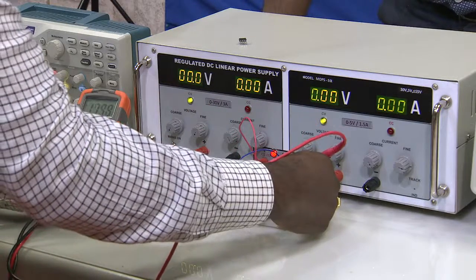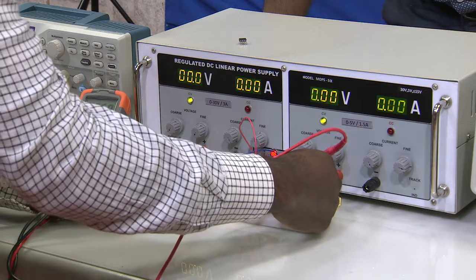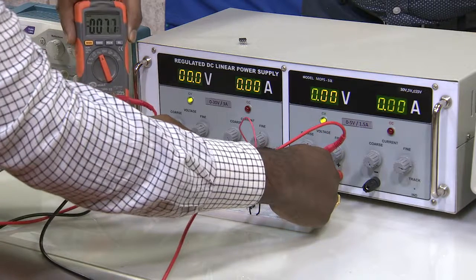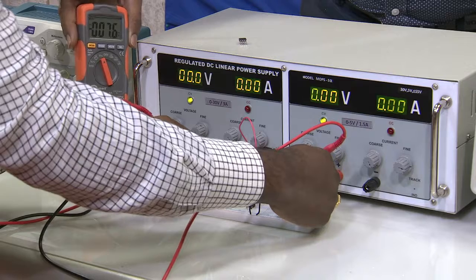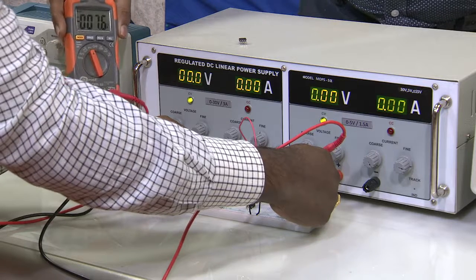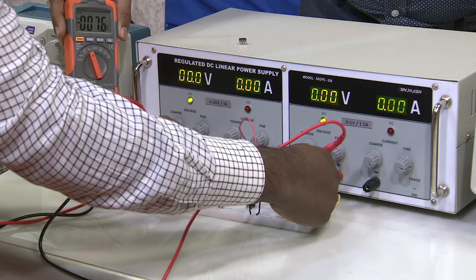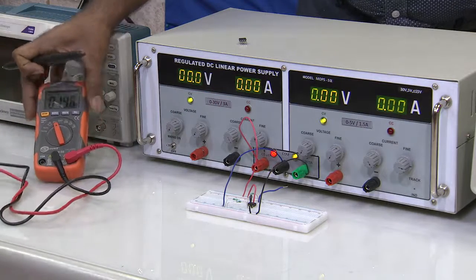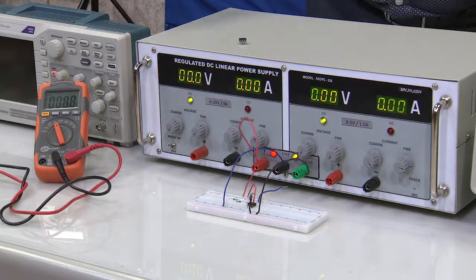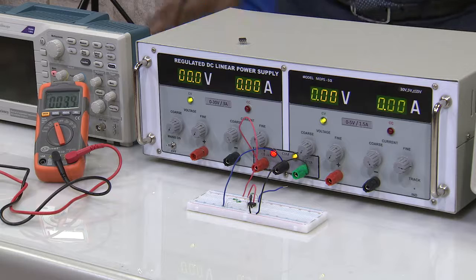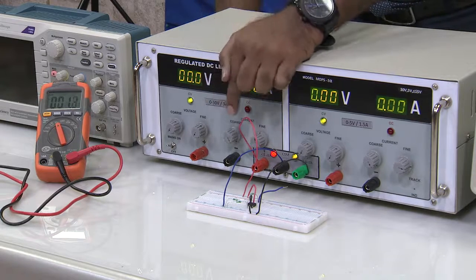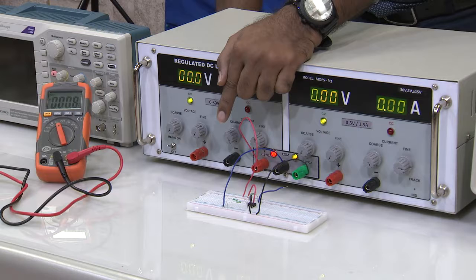So, he is connecting the positive to 6 and the other terminal to ground. What we see is some output voltage, 7.6 millivolts. Now, what should be the actual value? The output voltage should be 0, right, but in a practical op amp we are not able to get an output voltage of 0.